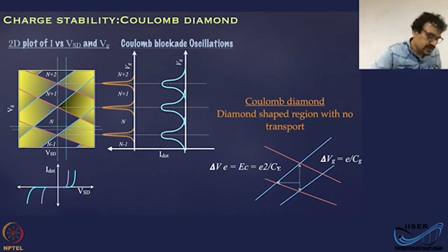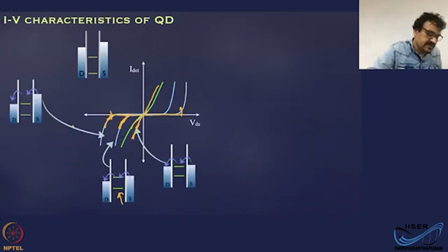And you can offset this by a small gate voltage as shown here. Then you can reduce the blockade region, and you can get current turned on at a lower bias voltage. This is basically the same thing we discussed in this slide, where you can apply various gate voltages and you can reduce the blockade region.